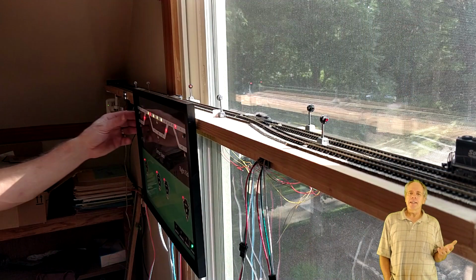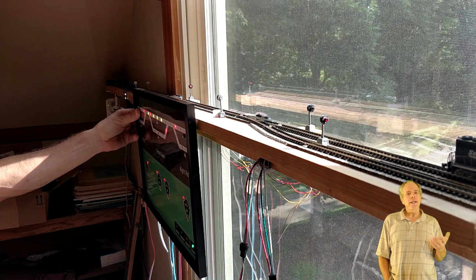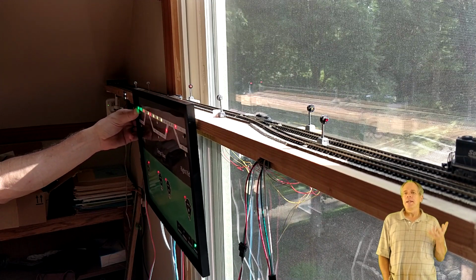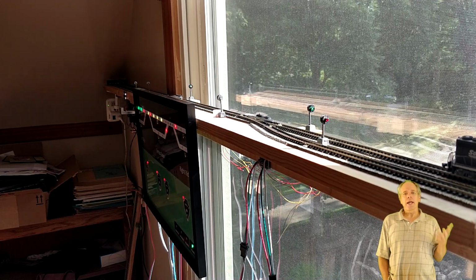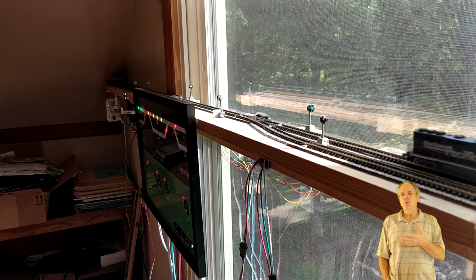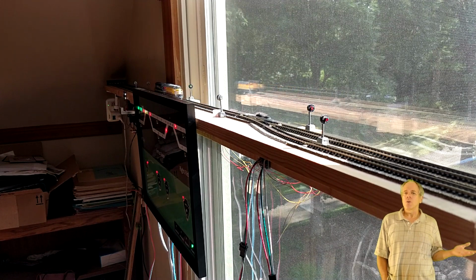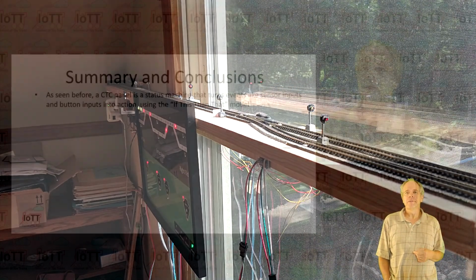The route is set and as soon as I double click button 178, the yard entry signal 811 is set to slow and the first ABS signal 809 in this example goes to track speed. The train then moves into track 11 and the route is cleared, signal 811 put back to stop and 809 changes to slow as it is part of the ABS zone. So that works as well and we can summarize what we have done.